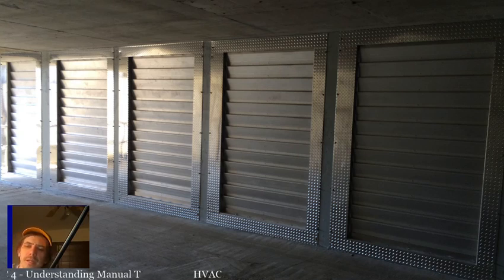So if you're getting a furnace that cycles on and off because it's getting too hot, the temperature limit switch is there in case the temperature gets too hot. And this goes for anything, not just a gas furnace. Electric heaters usually have some kind of temperature limit switch. Pretty much anything that produces heat is going to have some kind of limit switch. The issue is usually something to do with airflow, right?